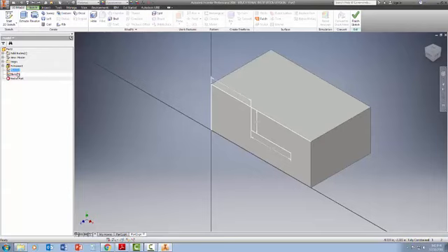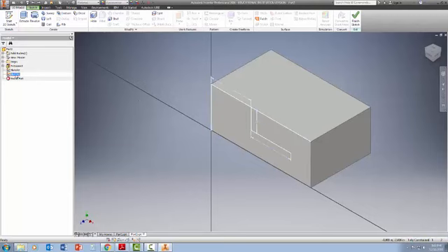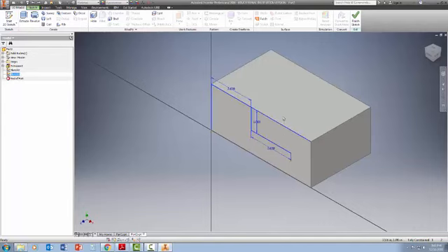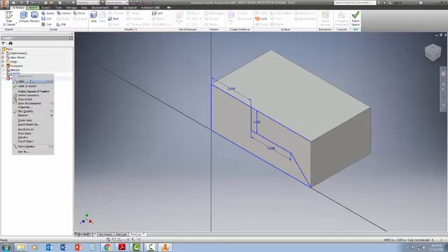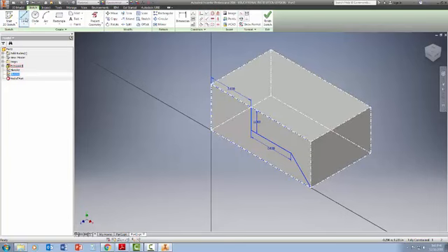If that happens, don't panic. What you can do is either go back, erase all of sketch 3 and just work on sketch 2, or you can make some lines in sketch 3 to make it think that it's part of sketch 3, and I'll explain that in just a second here. So I'm going to put that line back, and go to Sketch 3 and right click. Okay, and we're open, so actually I don't need to do that. We're open.